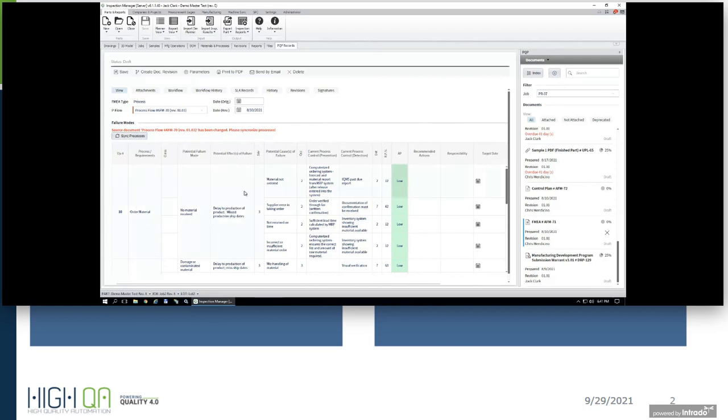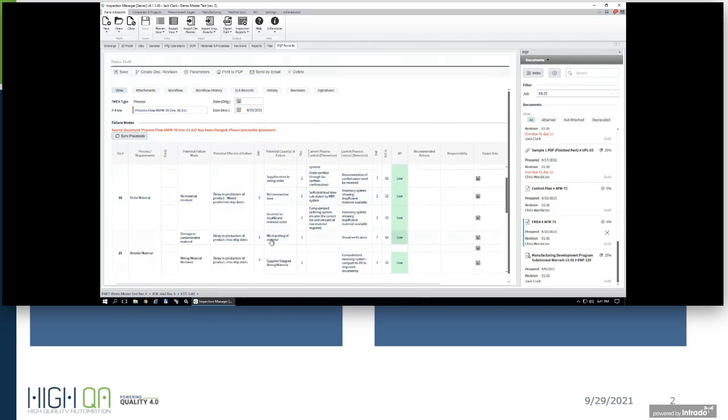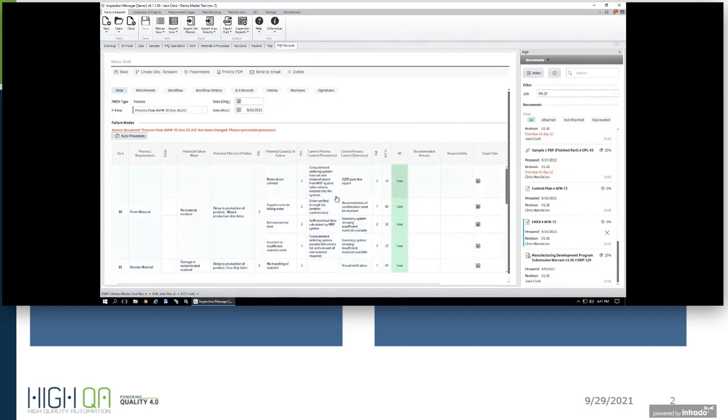Now, when we were talking about templating, I mentioned the process library, because when we generate our FMEAs, it's syncing from the operations that we defined. And for each operation, it pulls in all the potential failure mode, the potential effects, severity, and so on and so forth, right? Calculating our RPN values. Okay, so this is a system that we've spent a lot of time putting together and really optimizing, and it can do an amazing amount of automation within your facility as well, I'm sure.